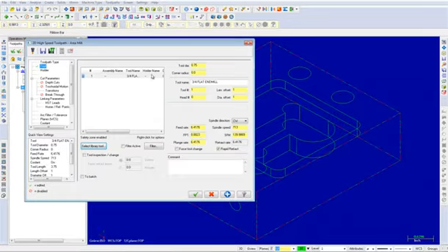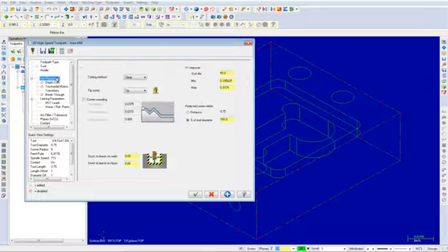Your tool will appear as shown. Input the following comment. Use area mill to machine the pocket. Once the comment has been entered, choose the Cut Parameters page. Make the following changes as shown. Enable corner rounding.